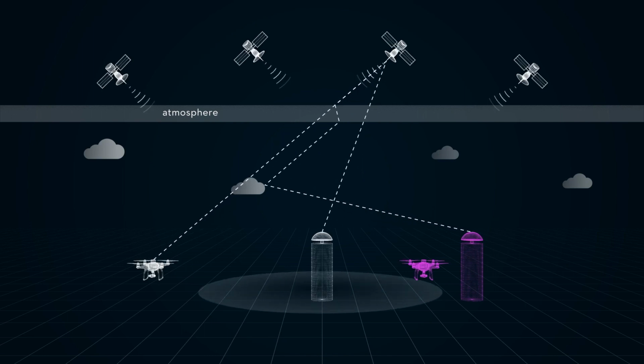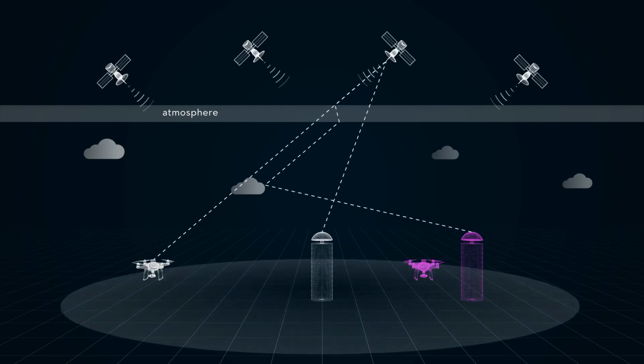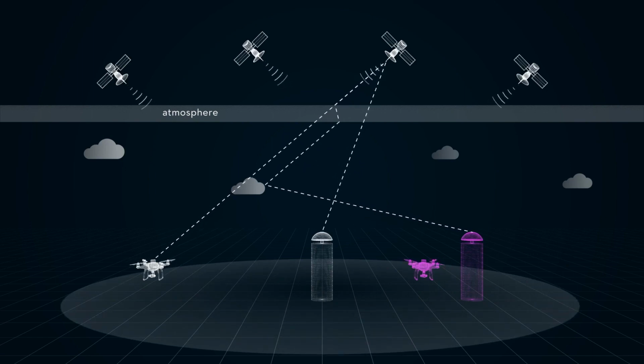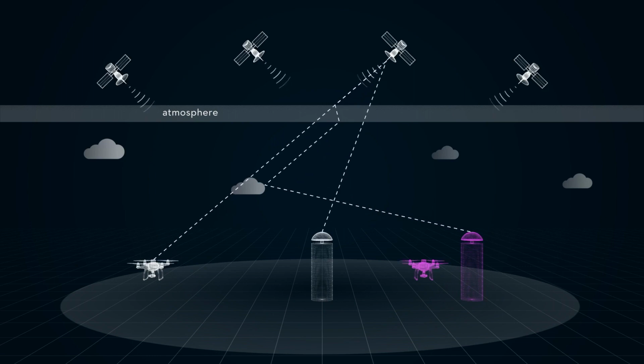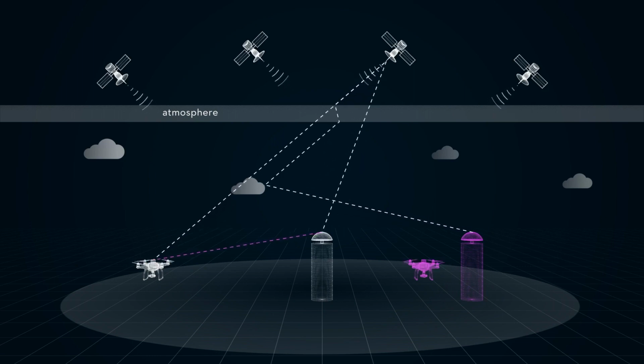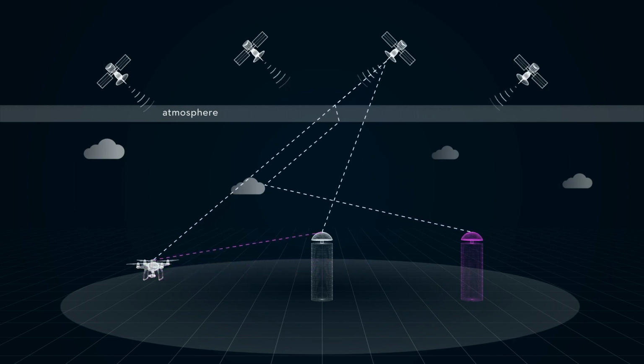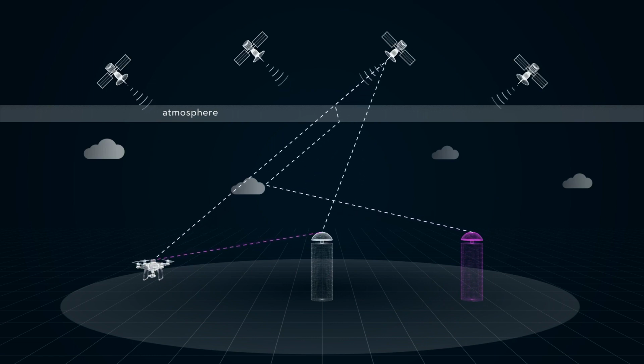The impacts of tropospheric and ionospheric movements on satellite positioning are basically consistent within 20 to 40 kilometers from the base station. Therefore, as long as the correction signals are sent to drones in real time, drones in this range can determine their accurate positions precise to the decimeter or even the centimeter. This is called real-time kinematic technology, also called RTK technology.